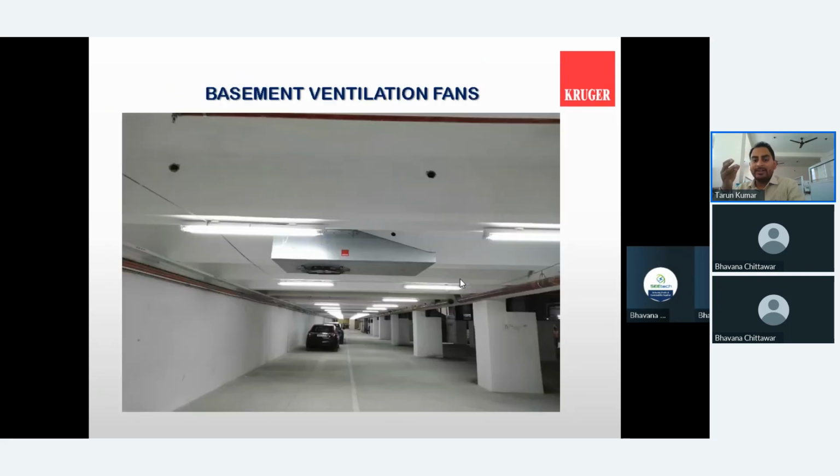So here you can see the site photograph of the installed fan, and the other feature you can see is that it is very low in height. The throw side of this jet fan, which will come below the beam, is only 120 mm, whereas with an axial jet fan, suppose you are using a 355 jet fan, the complete 355 size will come below the beam.